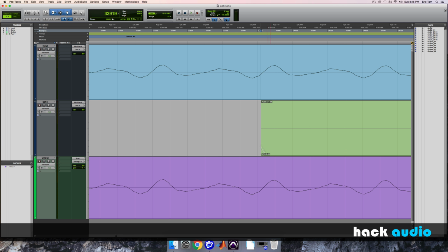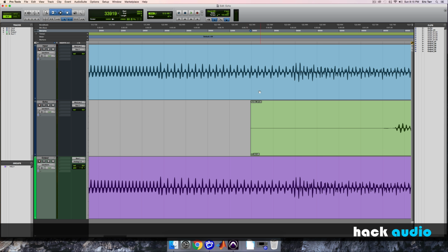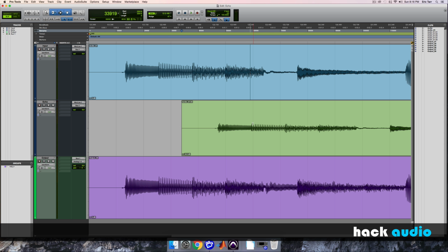Then we move on to our next one, 44,101, and then sample number 2 in order to get our output signal at 44,101. So what this allows us to do is index our signal at different sample numbers in order to create an echo. So here, rather than just using the current sample, we can actually use one from the past at the beginning of our signal in order to create the echo.